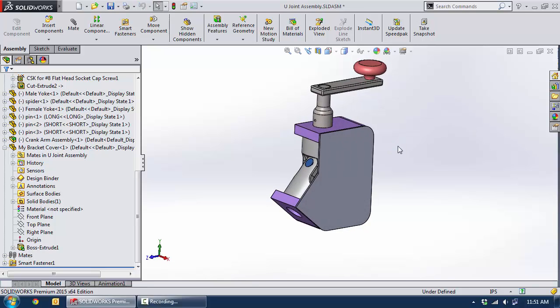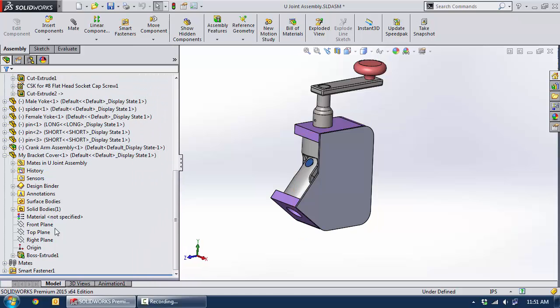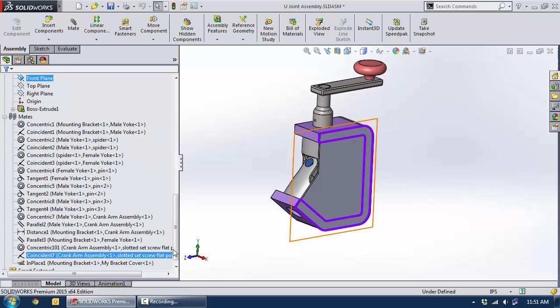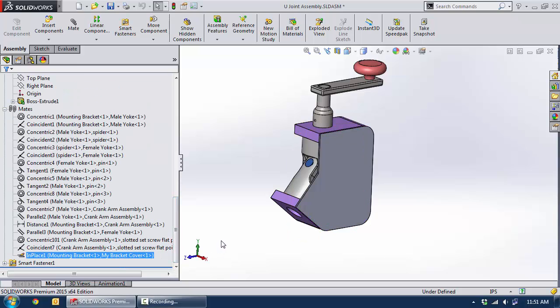Back in our assembly, again you see that the cross-part relations have been broken. There's absolutely no reference that this guy started life as a new part in this assembly. And the last thing that we would do is get rid of the special mate that was created when we executed on the new part.